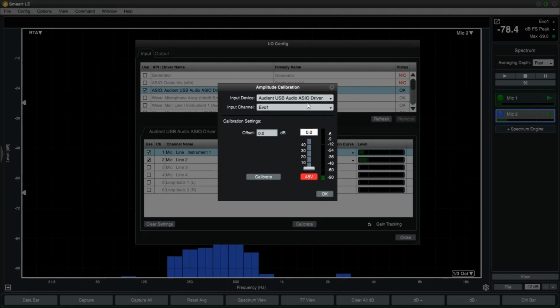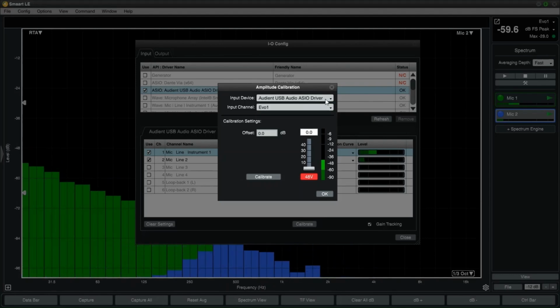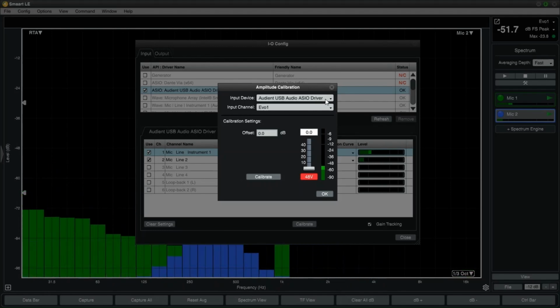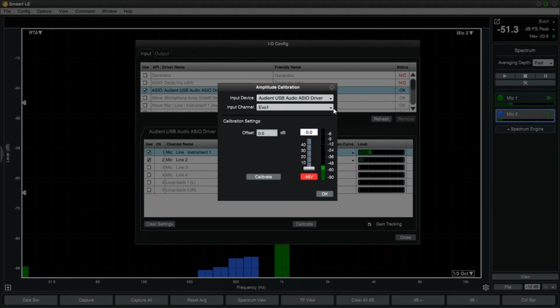At this stage, you want to position the microphone in the calibrator and turn it on. Select the value of SPL you want to use as the reference signal. In this case, we will select 94 dB. The meter on the right of this window should show you incoming signal. Take note that this signal is representing your system headroom. If you turn up your interface gain, you will decrease the allowed headroom. It is always preferred to do calibration with maximum headroom to avoid clipping your system with the content you want to measure.